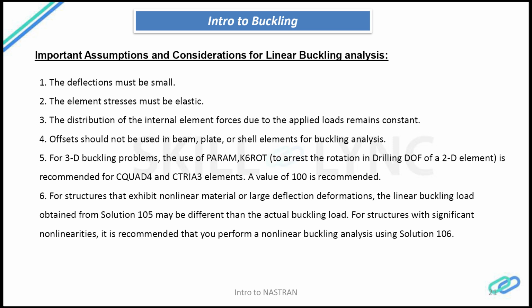I'm sorry, I repeat. If you're not getting the results you want from the linear buckling analysis, it is recommended that you perform the nonlinear buckling analysis first, and then you see the buckling load values, eigenvalues and eigenvectors. Then you ascertain how to solve the problem.